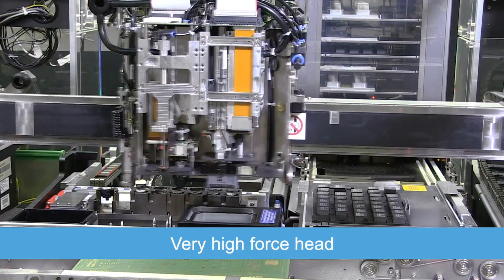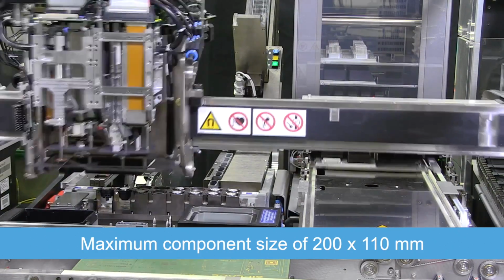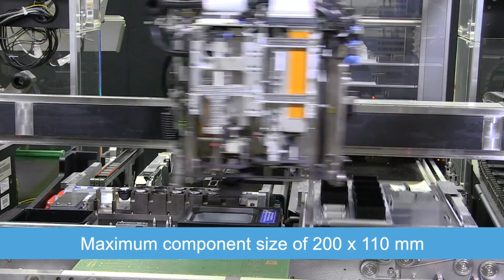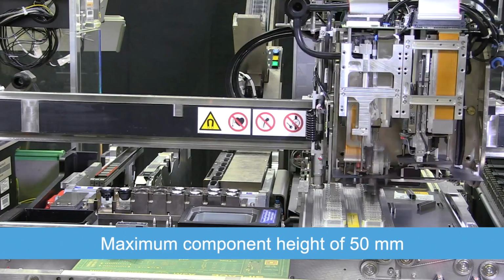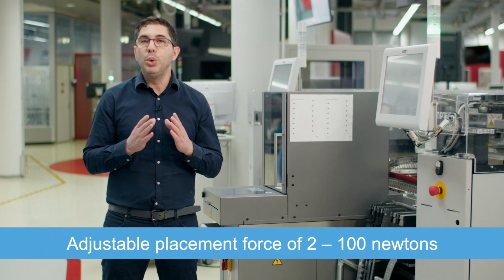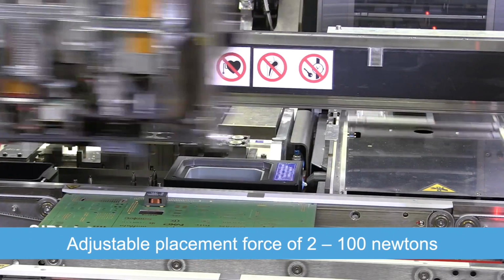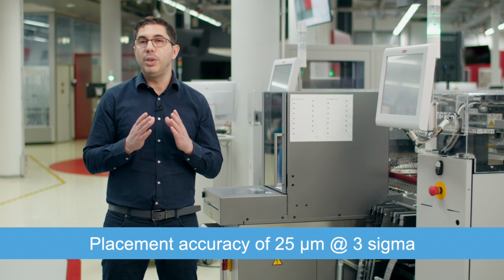And at the end, a vision system which is capable of handling all these different odd-shape components. The very high force twin head can handle components up to 200 mm by 110 mm. The maximum component weight is up to 300 grams and the maximum component height is 50 mm. The placement forces can be adjusted from 2 Newton up to 100 Newton. And the placement accuracy in combination with a very high force twin head is 25 microns at 3 sigma.